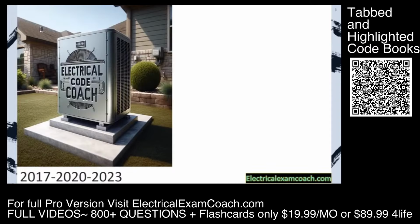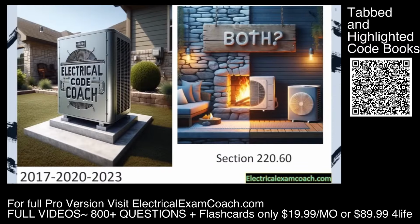Today we're going to be calculating HVAC/VAs for our heating, venting, and cooling. The only code that we need to be familiar with is 220.60, and that's talking about non-coincidental loads. Let me explain what I mean. Usually in a typical house, you're not going to be running the heating and the cooling at the same time. So the code has made provisions for our whole house load calc that we only have to count the larger of the two. Let's get to it.